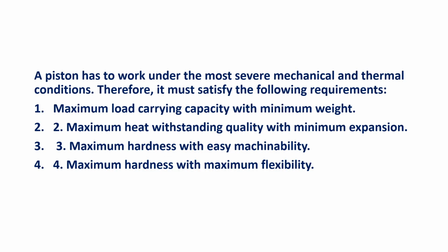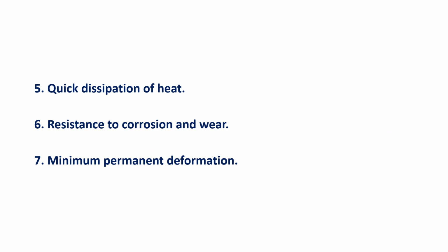What are the requirements that the piston has to meet? It has to carry the maximum load with minimum weight. It has to withstand the heat with minimum expansion, and have maximum hardness with easy machinability, and maximum hardness with maximum flexibility. Very important, heat should be quickly dissipated. Though you have cooling chambers, the heat dissipation should be high, because at high temperatures the material may expand, so you have to avoid these losses. It should be resistant to corrosion and wear, and we should have minimum permanent deformation, etc.